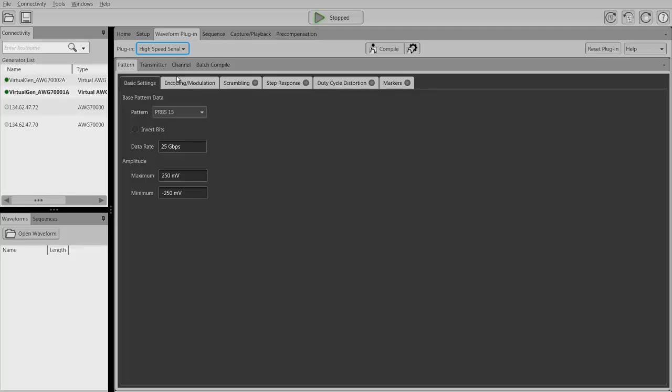So in this case, many customers want to create jitter profiles that enable them to test their receiver in the worst case conditions. So using an AWG to create specific test environments such that you have a certain amount of jitter, a certain amount of ISI, a certain amount of random noise, a certain amount of random jitter, and in some cases spread spectrum clocking is also required to be tested in these high-speed serial standards.